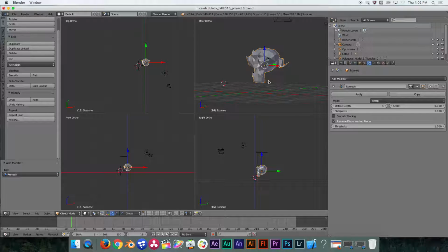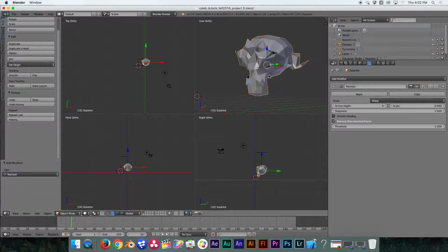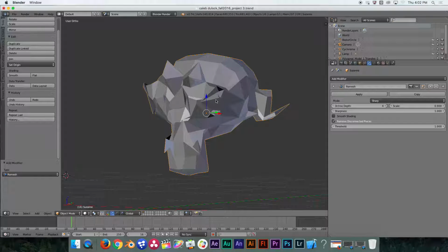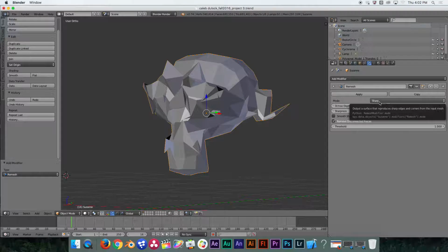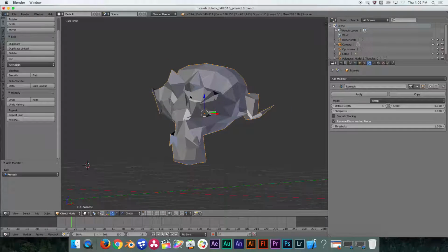And when you turn on remesh initially, what you see happen to your model is that it actually applies part of this filter. It has 3 separate modes: sharp, smooth, and blocks. And sharp kind of looks like what it does automatically to your model. It tries to sharpen off any rounded polygon structures, which you can change with these settings in the property panel.